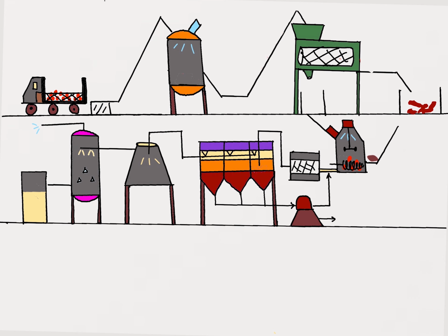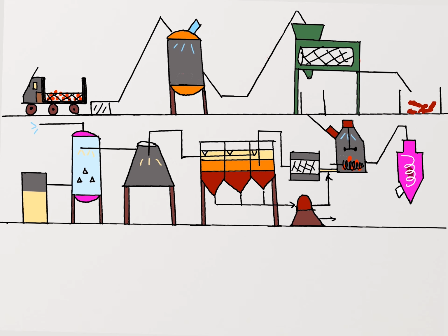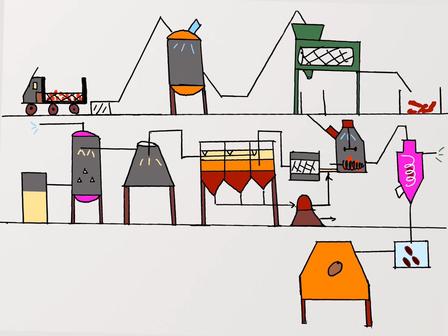The press cake from the screw press is then fed into a vertical column called a depericarper, which uses a cyclone of air to separate fiber from nut. The nut will enter the next stage, which is called nut conditioning. This is achieved by first drying the nuts to loosen the kernels and then cooling them to harden the shell. Then a centrifugal cracker is used to crack the nuts and remove the kernel.